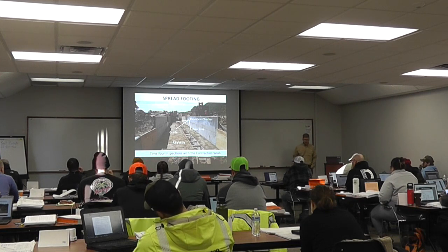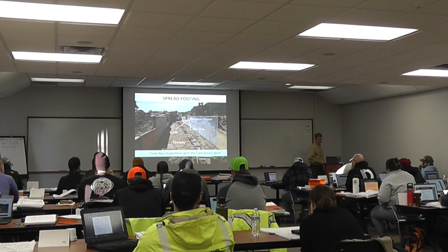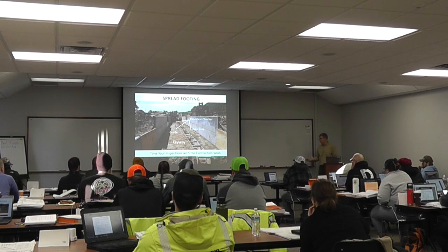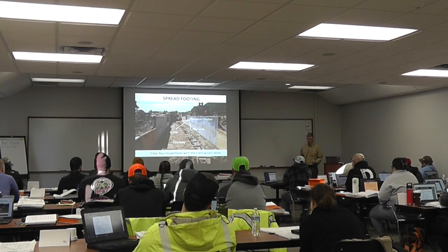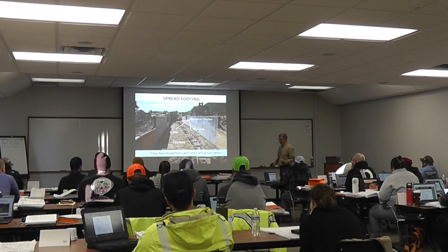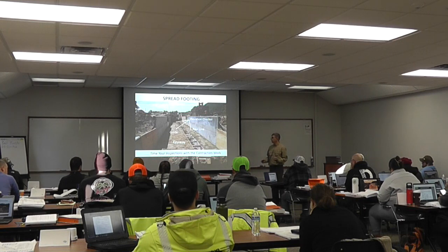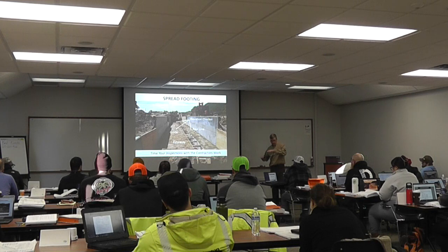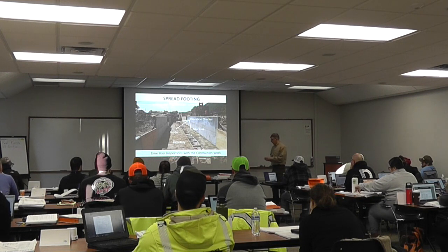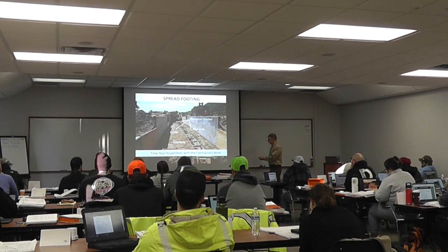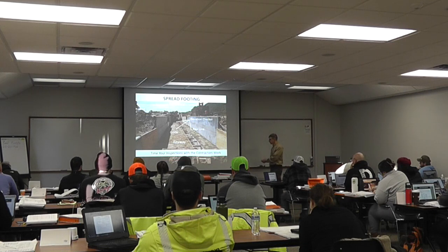So again, here are some things. We're getting ready to put some rebar in. Are they ready to put rebar? The center thing in here is called a shear key. You'll see this sometimes in retaining walls and occasionally in abutments. But its purpose is literally like a shear key. It's helping against that sliding type of failure. It provides an additional little block down there. That thing will get reinforced. It's not just unreinforced concrete, but it'll be a reinforced zone.